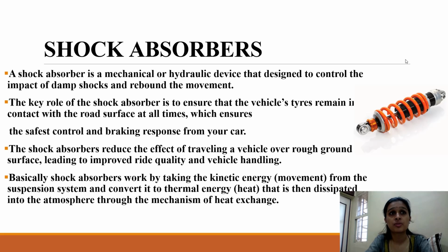Also, the braking response of the car needs to be taken care of. So the shock absorbers are used to reduce the effect of traveling through a rough surface or a more stiff surface, which leads to an improved quality of ride and also proper handling of our vehicle. Basically, shock absorbers work by taking the kinetic energy or the movement of the vehicle from the suspension system and converting it into thermal energy, which is nothing but heat, and this heat is dissipated into the atmosphere through a mechanism called heat exchange.